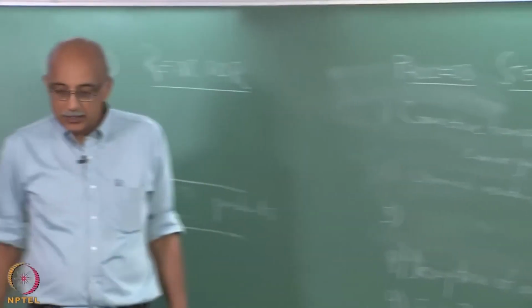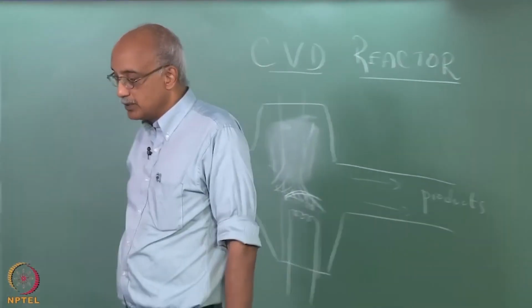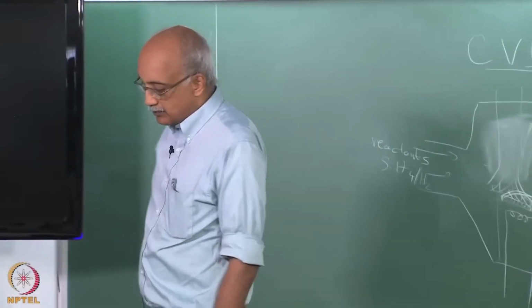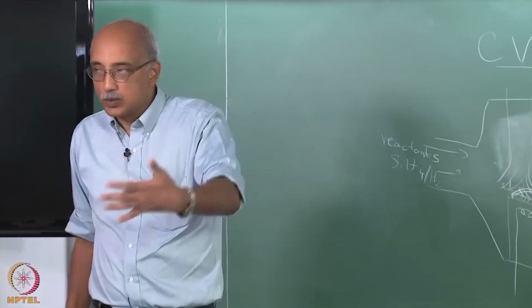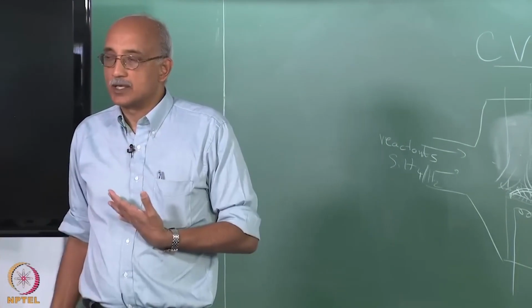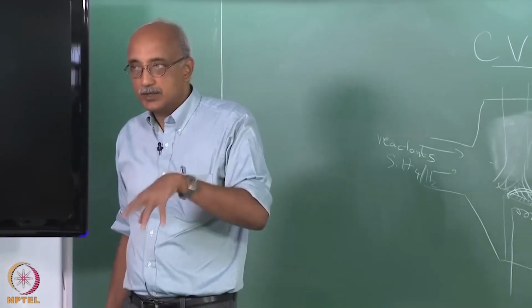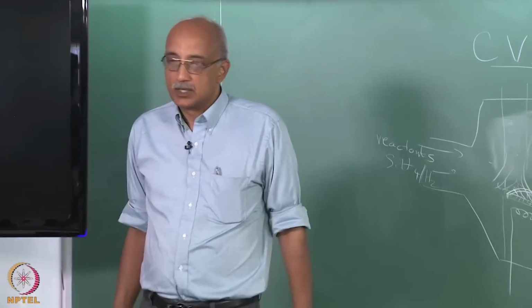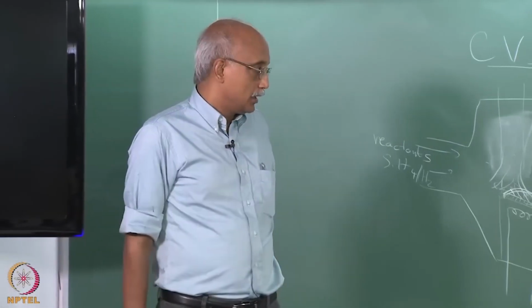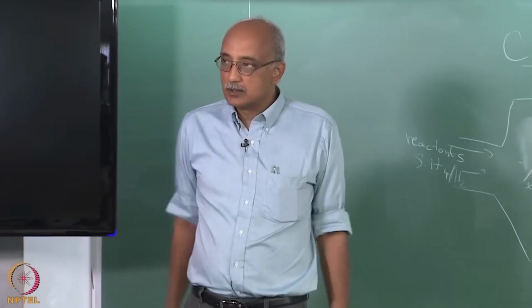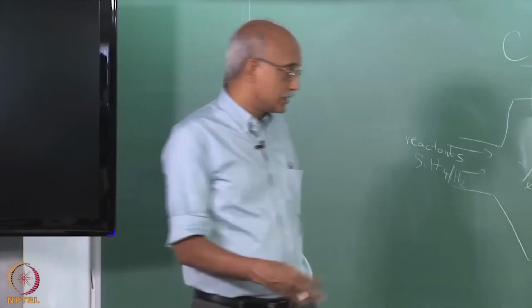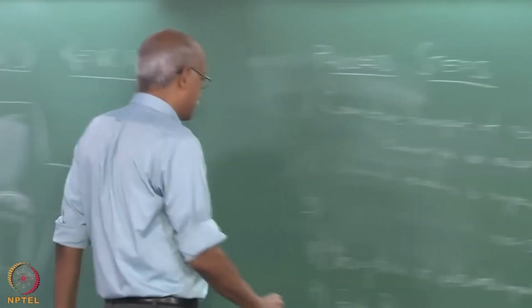So, the exiting of these desorbed impurities from the boundary layer to the outside is another important step. Otherwise, again, they will stick around and keep getting readsorbed onto the substrate. So, as soon as possible, you get them out of the boundary layer, and then the last step, of course, is exhaust.